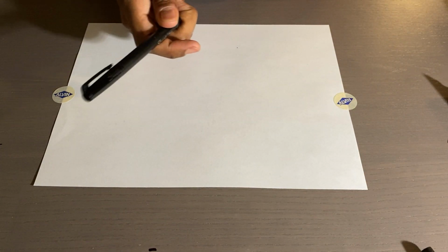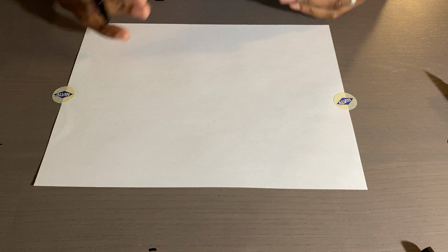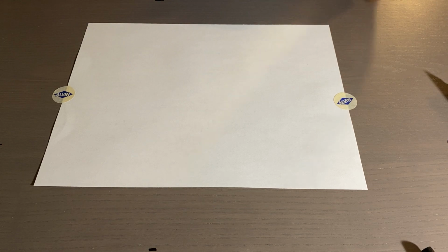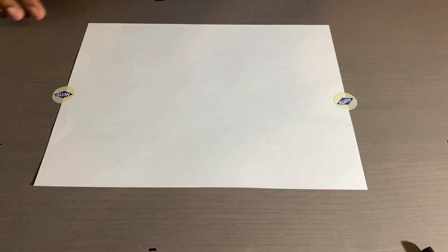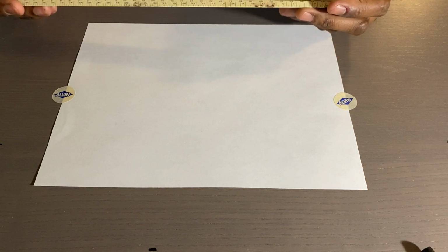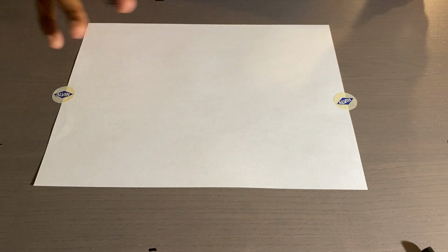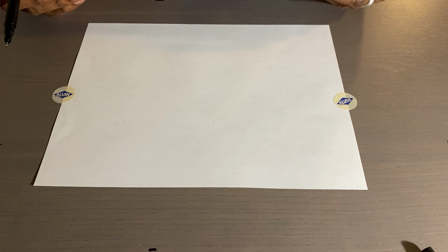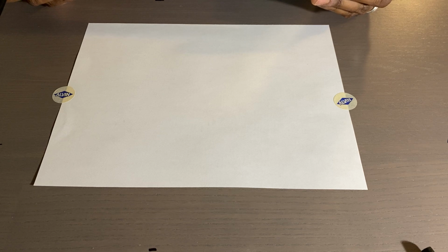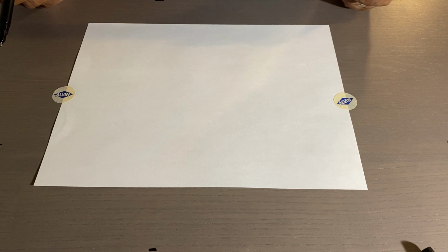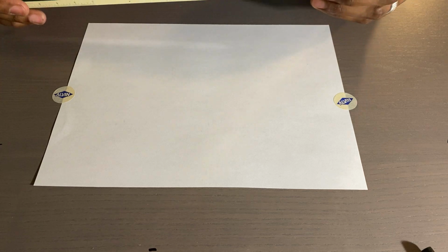And then the first thing I do, I'm trying to get organized here, is I take my thin pen, or my light pen, and we're going to begin the process of laying out the dimensions of our parcel. Okay, so the first thing you want to do is pick a good scale. If you're using an architectural scale, smaller is better, especially at this level of development. I think that developing at 1/8 inch or 3/32 of an inch would be a sufficient scale. So let's measure it out here.